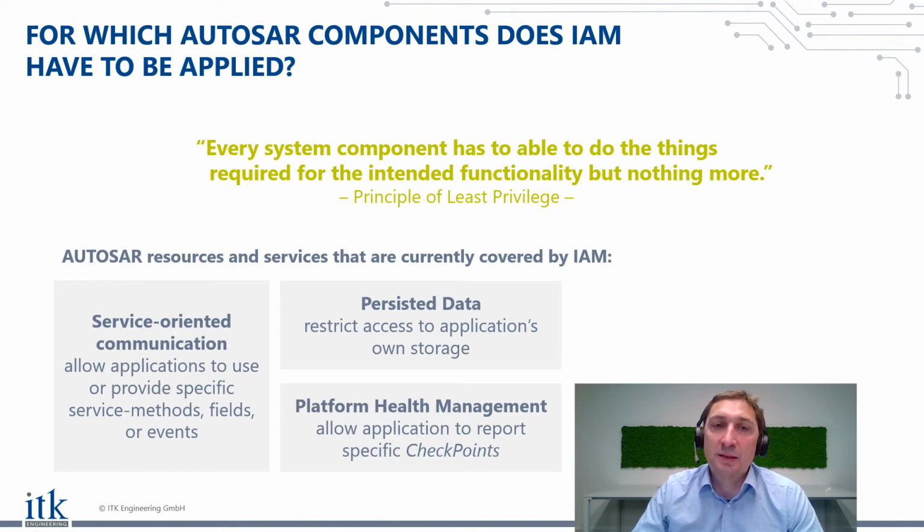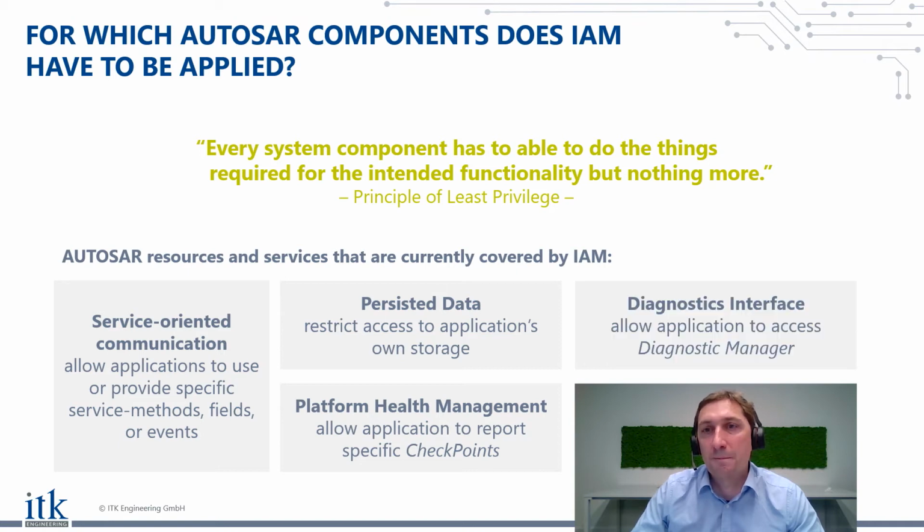And there is platform health management. Platform health management is a distributed state machine which keeps track of the state of your ECU across different applications. And IAM makes sure that applications reporting states can be identified in the first place, and that only legitimate states are reported by those applications.